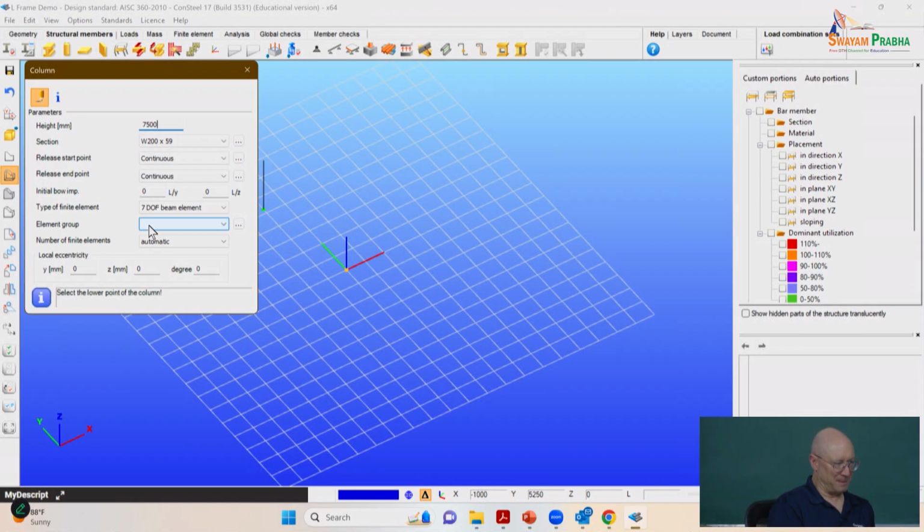How do you define the warping? Yeah, so the warping, if it's an I section, it's simplest. So warping is simply a cross bending of the flanges. So warping is when the flanges are bending in opposite directions. So you can add that to the lateral bending of the flanges.